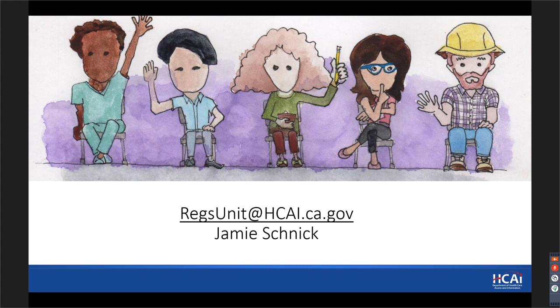The intent is that the new work follows the code. The code requires short circuit ratings. Obviously, if you're doing anything that's going to affect the short circuit rating, if you're adding motors, adding transformers, or, like we talked about, supplementing the normal power service with distributed energy resources, you would need to go ahead and do the calc and label it.